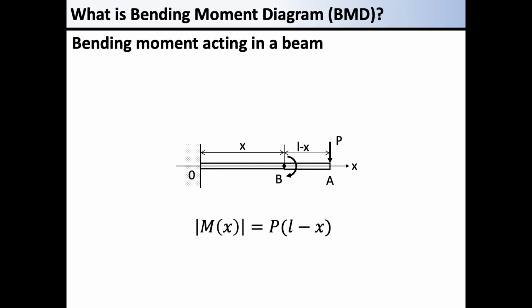We are also considering the situation of slightly shorter arm length. We now focus on the bending moment at point B on the x-axis. Since we are pushing the beam vertically at P from the left, we will have a bending moment that is determined by the product of the load and the arm length. The length of this arm is the length of the beam, L minus x. So, the magnitude of the bending moment acting on this point is given by the equation.